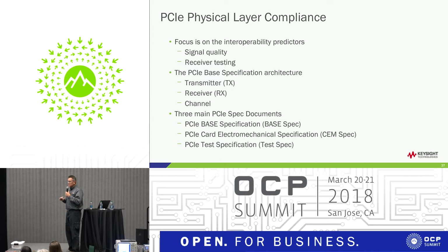We want to do the testing necessary to ensure that a motherboard made by one vendor will work and interoperate with an add-in card, a NIC, or even a storage device made by another vendor. The two things we do to help enable that are focusing on signal quality for the transmitter side and then receiver testing.